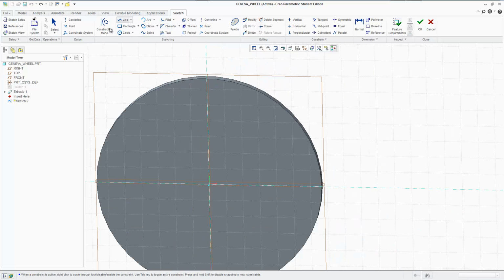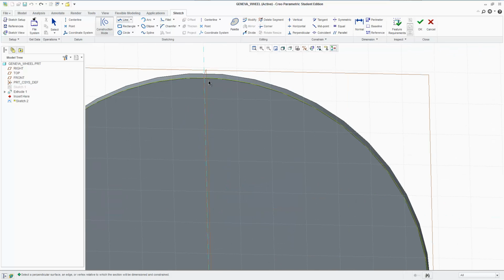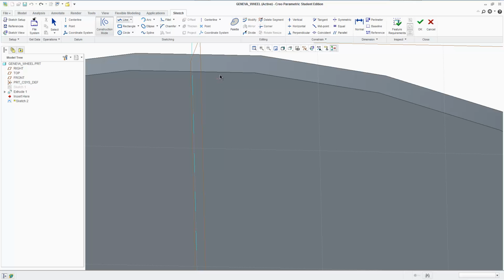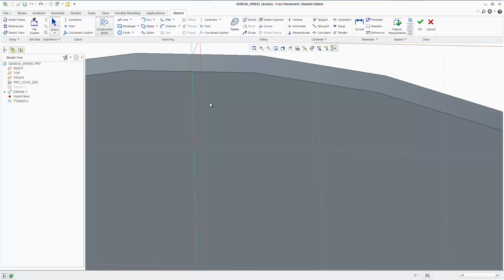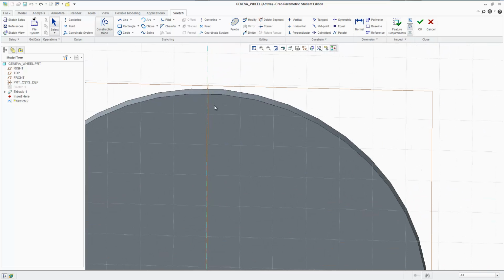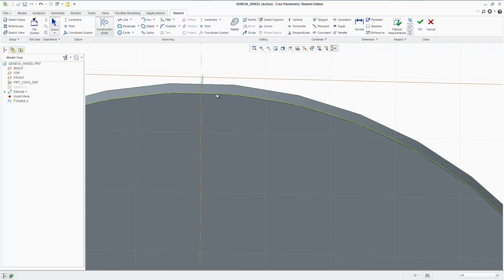So I'm going to try to make a line, and I'm going to try to get somewhere around this point to have my slot. So let's make that slot, and first I'm going to select this as a reference. And the way to do that is you can click references and select your references and do whatever, but I like to do it a little differently. I hold down Alt and then I click wherever I want it to be my reference. So see right here how it's activating right now. I have Alt held and I click it. Now it's my reference.